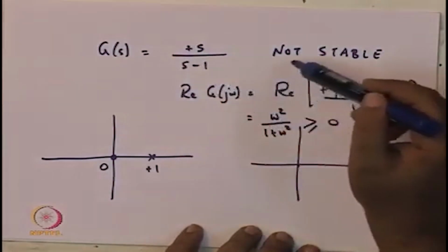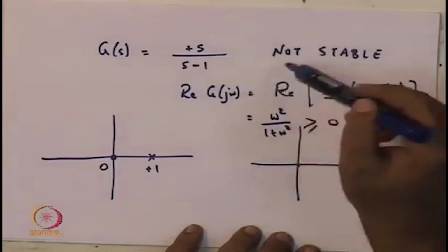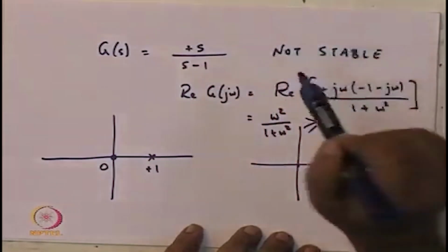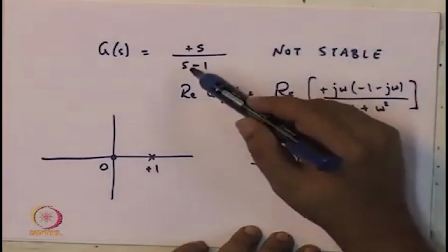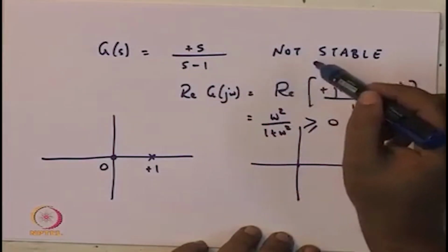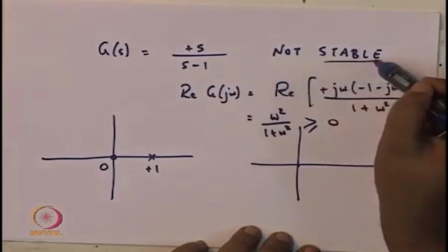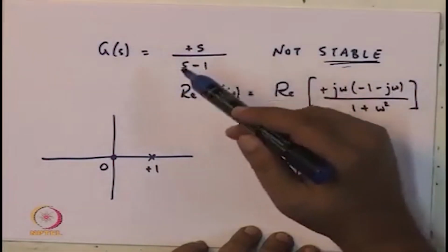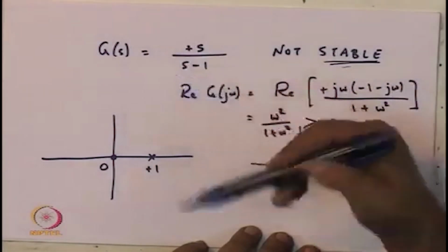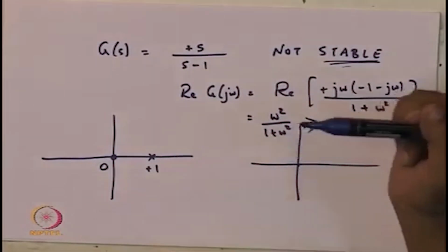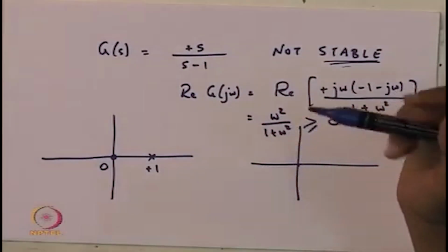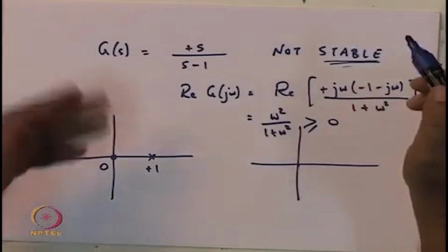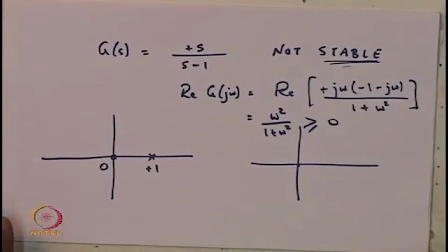But if in addition you also put in the condition of stability, this is not stable, therefore, this transfer function is not positive real. Okay. Now, the question is, why was this condition of stability brought in to associate these transfer functions with passivity? Now, that is completely dependent on what one would call the storage functions. Okay.